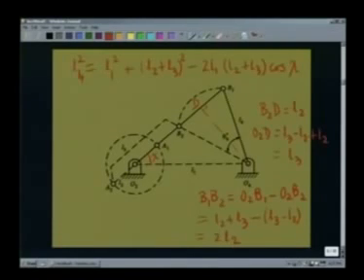So, cosine chi is L3, that is O2D, divided by O2O4, that is L1. So, we substitute this L3 by L1 here, and if we substitute this, we can easily show we will get L1 squared plus L2 squared will be same as L3 squared plus L4 squared.